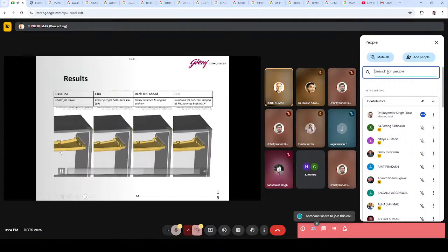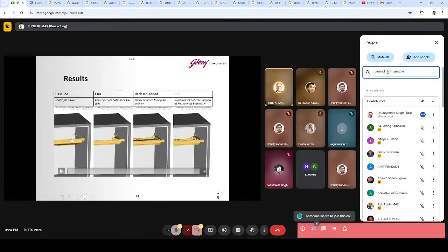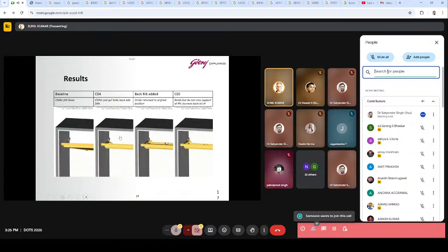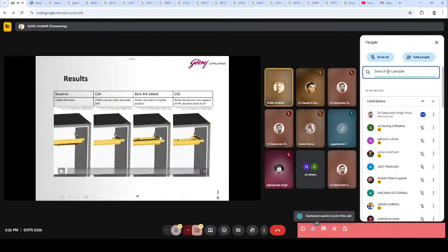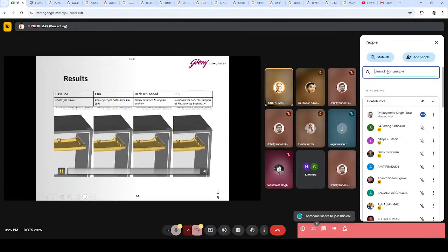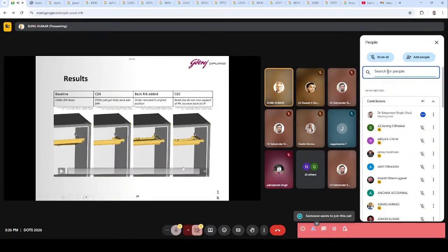During the drop test, this crisper is falling out. If you see in the first slide, it falls from the refrigerator during transportation and even the drop test. So by adding some changes in the design, as you see, these are the design changes in iteration 2. We made these design changes, and these for handling. We also made it stiffer, and made more design changes to avoid it falling. In the end, if you see the third and fourth options, we went with the third option. The falling was reduced, and in physical testing it also got avoided during the drop test and transportation.